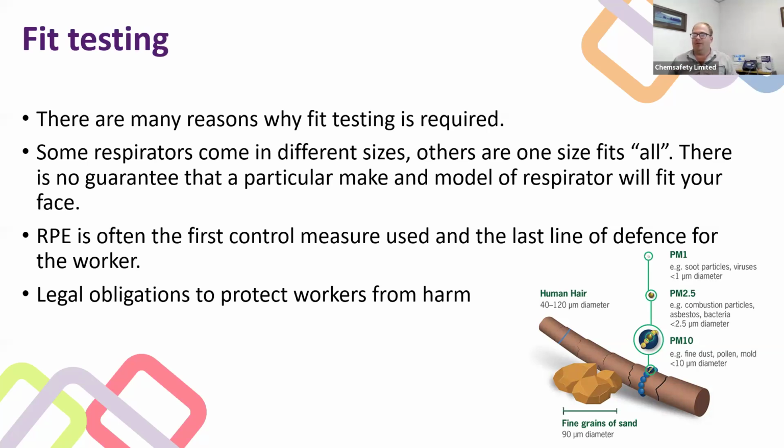And there's no one size, even for the masks that come in one size fits all. It's designed for most face shapes. When they do the manufacturing, there's a panel of different face shapes and they test it all and try to determine the fit, but there's no guarantee that your particular face will fit that particular respirator. And as I think I mentioned earlier when we were doing the word cloud exercise, respiratory protection equipment is often the first control measure considered, but it's the last line of defense. So if this fails, I'm now breathing in the thing I'm trying to protect myself against. So I want to have those other controls, and I want to make sure that this control is less likely to fail because it provides a good fit for me.